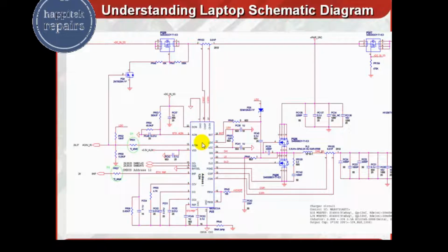Every 30-40 pages have this type of diagram. Here it is written which voltage, which pin number is there. You can identify the pin number, the component, the output, where the output is going, on which page number, and at that page number what it is going to.